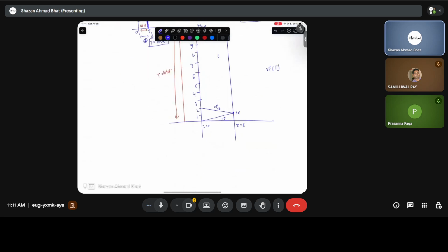Okay, and then again it will be reflected towards the load at time 3 td. Again the value will be V1 plus divided by 4. So again it will be reflected. It will be V1 plus divided by 8. It will be again reflected, so on and so forth. So that's going to happen.